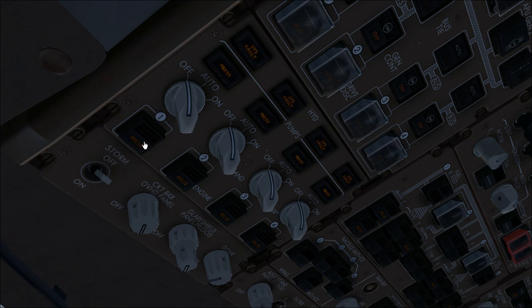Engine pump switches must be selected on, and the press light must remain on because we don't have any pressure coming out from the pumps on the engine accessory gearbox, so that's fine. About the demand pumps themselves, the pumps are different. You have electrical power pumps in the second and third systems, and the demand pumps on system 1 and system 4 are air driven. This means that sometimes, because they are air driven, the fluid from system 4, if it is pressurized before system 1, can mix the fluid between the two systems, system 4 and system 1.